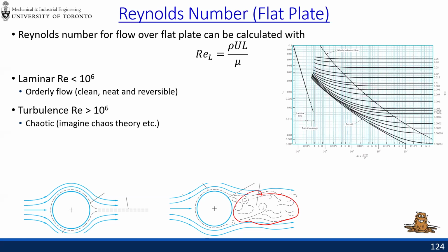Anyway, so now some of you might have recognized that the Reynolds number to switch over to turbulence doesn't match what we have from chapter 6. Right? In chapter 6, the Reynolds number switches over a lot sooner. That's because if you look at the Reynolds number from a Moody chart, that's rho V D, where D is the diameter of the duct. So when you look at different geometry, different flow, you use different Reynolds numbers. And subsequently, quite often, the Reynolds numbers to transition are also different.